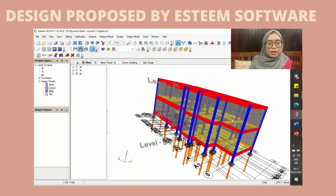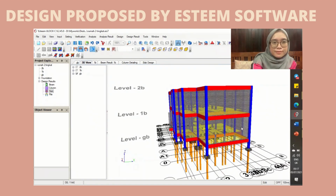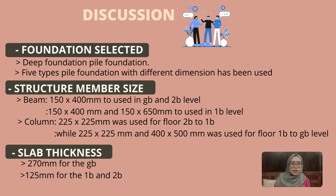3D view that we have designed for this project. For the foundation, we are using a foundation that has been divided into two, which is pile foundation and drilled shaft. In this project, we designed by using pile foundation, which is 5 types of pile foundation with different dimensions, marked as P1, P2, P3, P4 and P5. The 5 types of dimensions used were different, but the pile size for all 5 foundations was the same, which is 150 x 150 mm with 20 tons of pile capacity.